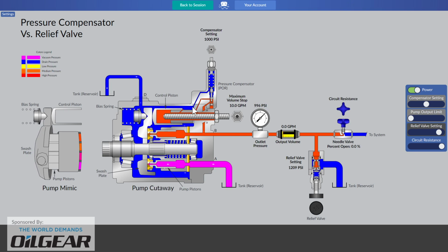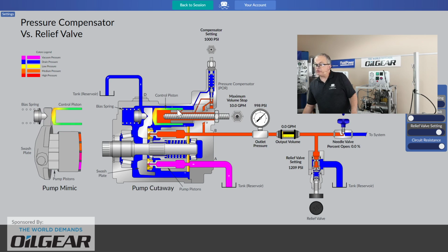So there it is. We also notice that when the control piston gets to its maximum length, just so that we don't go past 0 degrees on the swash plate, just so that we don't crack this pump in half, there may be on the control piston a relief orifice limiting how far that control piston can travel, and you may notice a sudden surge in case drain flow as that orifice is uncovered. And so that's a reason why you may see a sudden spike in case drain flow if you're measuring it, and we'll talk about that some more in a moment.